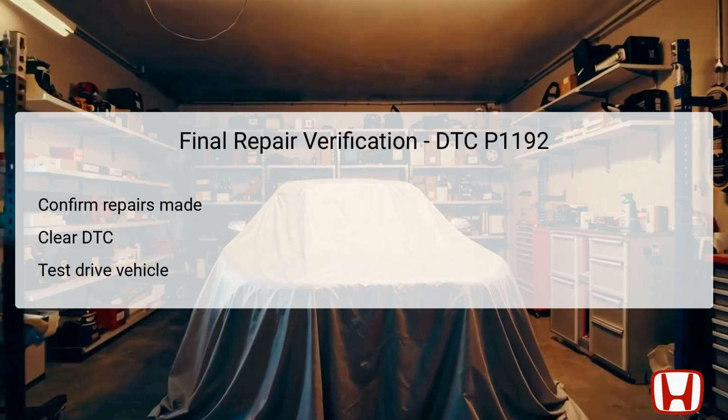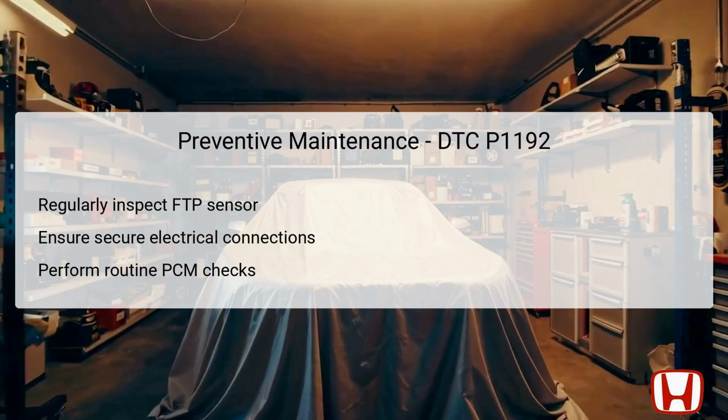After clearing the codes, it's essential to take the vehicle for a test drive under various operating conditions to monitor how it responds, and to confirm that the DTC does not reappear. This step is fundamental in ensuring that the solution effectively resolved the low voltage condition and that the vehicle operates without hindrance, restoring optimal engine functionality. Engaging in preventive maintenance is vital for preventing issues like DTC P1192 from reoccurring.